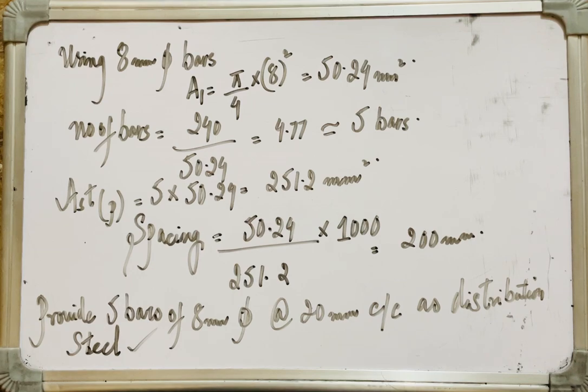उसके बाद मेरे पास इलास्टिक डिज़ाइन कोफिशिएंट्स थे. उसके बाद मैंने ये भी चेक किया कि जितनी मैंने इफेक्टिव डेप्थ प्रोवाइड की है क्या वो सेफ है कि नहीं. उसके बाद मैंने अपना निकाला रीइंफोर्समेंट डिटेल्स क्या देंगी अब अपने स्लैब को, बोथ along the shorter span and along the longer span. Shorter span is the main reinforcement, along the longer span is my longitudinal reinforcement. उसके लिए भी क्या प्रोवाइड करना है वो वगैरह हमने सब डिज़ाइन कर रखा. आखिर में डिस्ट्रीब्यूशन स्टील क्या लगाएंगे वो भी डिज़ाइन करके रखा.